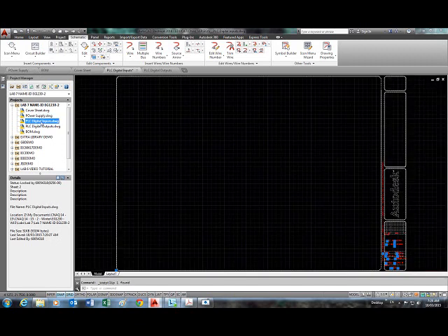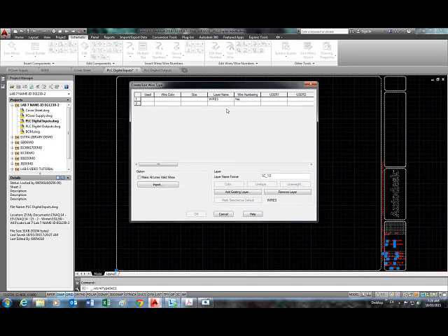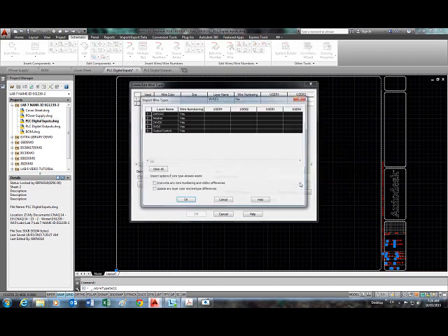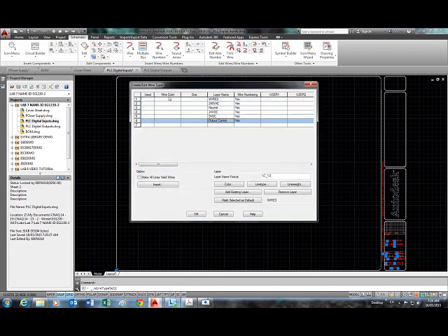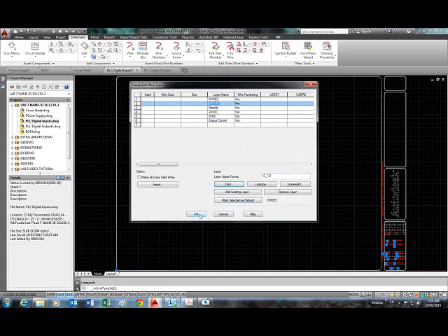Now we go to the next drawing, and instead of having to create all of these again, we'll just say import from power supply, open, and there they are. We'll just say OK. And notice that the wire colors are not, at least the codes are not imported, but the actual wire colors are imported, and this also kept wires. So 240 volts AC, you'll see that it's still red, and the line weights are still there.